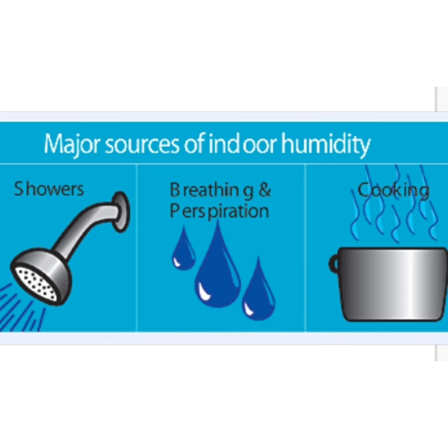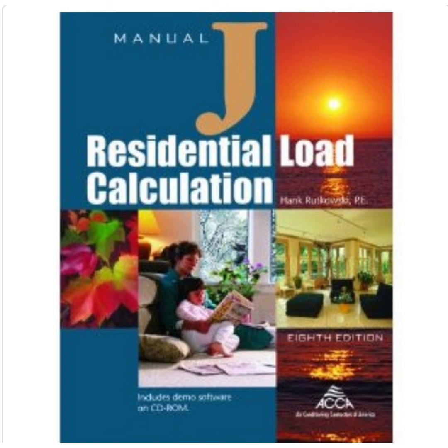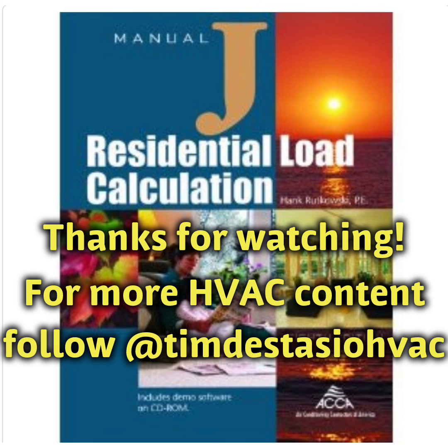Most humidifier manufacturers actually give you a sizing chart. So you may think, why are we worrying about these calculations? Well, those sizing charts only include a very specific scenario, which may not be your scenario. If you undersize a humidifier, your customer is not going to be very happy, and trust me, you don't want that call. If you oversize a steam humidifier, it may waste energy because that water has to be warmed up all over again in between cycles. So it's really important to understand what goes into the humidification load of a building, and that's where understanding system design and looking at Manual J and the other ACCA manuals will help you be a better contractor.